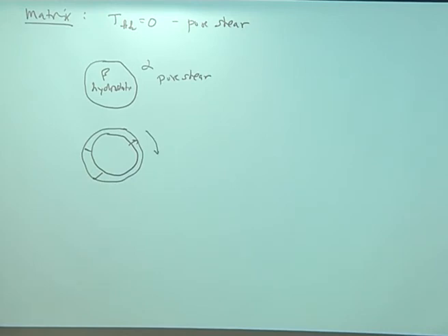In other words, the matrix wants to slide against one another like this, and it's bigger at the interface, and it decays. It doesn't go out uniformly; it wants to slide. It doesn't actually slide, but it gives rise to a shear stress, and so you have pure shear out here, and it's constant in here as well.